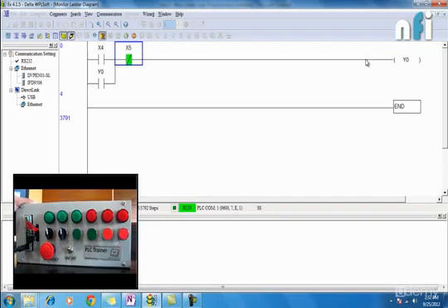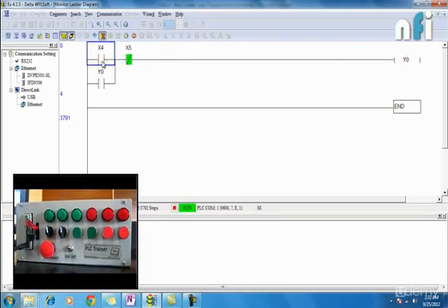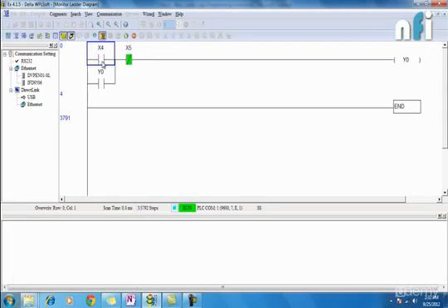This is widely used in industry, the latching of motors, contactors, solenoid valves. This is internally how it is done. Again, my wiring is the same. I'm just changing the program. I'm using internal relays and internal contacts to latch and unlatch the circuits. Otherwise, to perform this without a PLC, you would have to use a relay and its NO and NC contacts. To avoid that, we avoid the relay and use the same principle inside a PLC. So that's how it works.